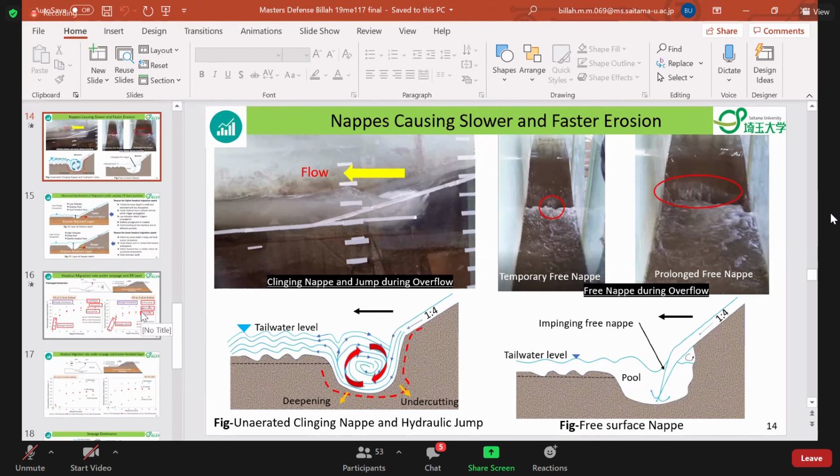I have mentioned that overtopping is not considered in the design of the embankment. From this experiment, we know how the erosion takes place, and then we can predict the breaching so that we can plan for flood evacuation. But I could not focus on preventive measures. I tried to understand the phenomena. This is just a proof of concept. I see, understood. Thank you very much.